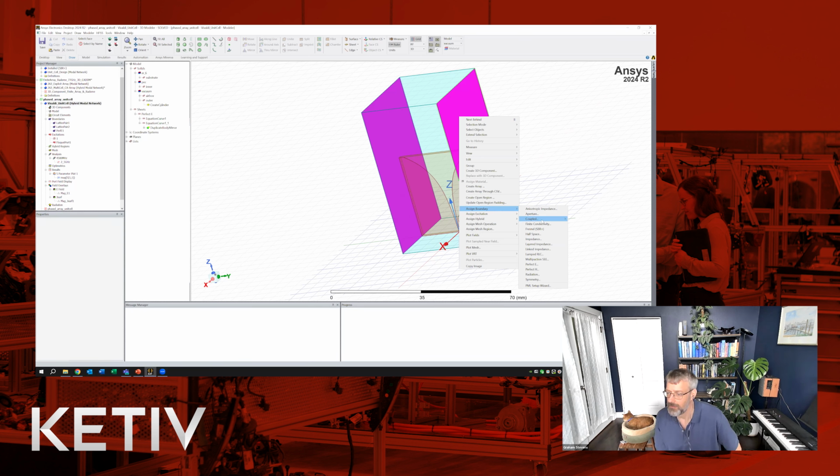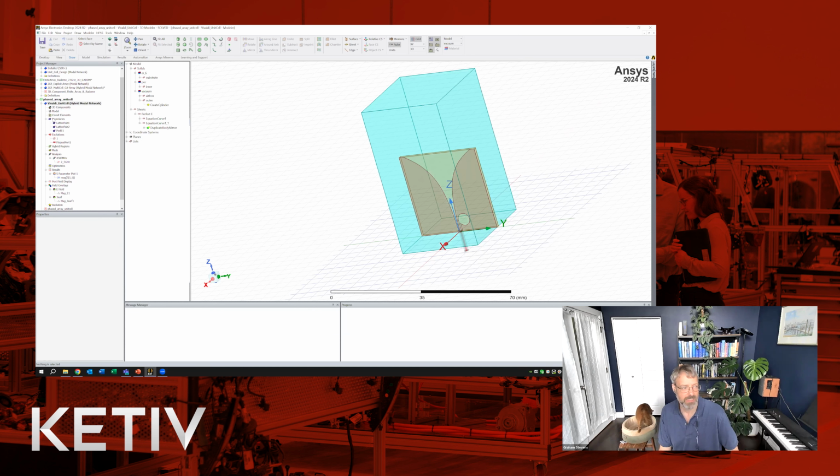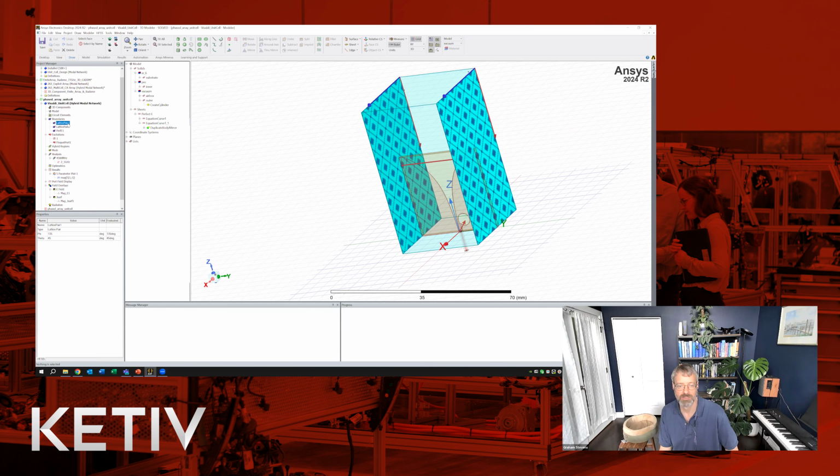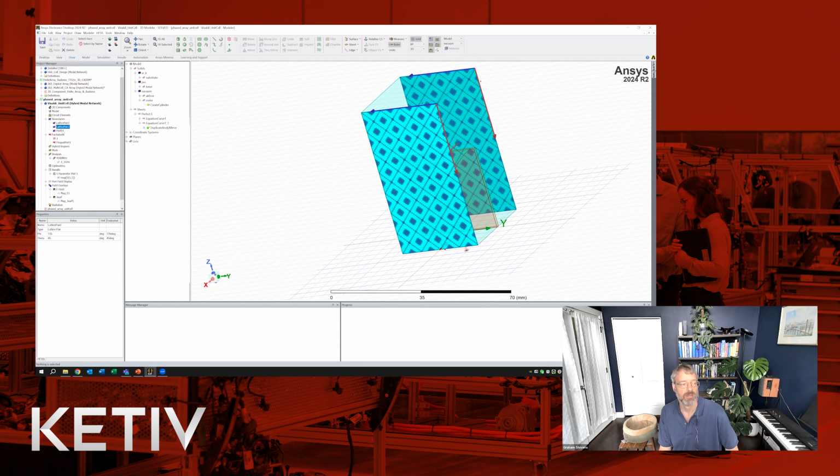And you can also auto-identify lattice pairs. So if you have a standard box, HFSS does a pretty good job of just identifying the lattice pairs and setting up everything automatically. This is a big improvement compared to the master-slave relationship we had probably a decade ago in terms of setup. Click on that, and you'll have your lattice pairs set up here.